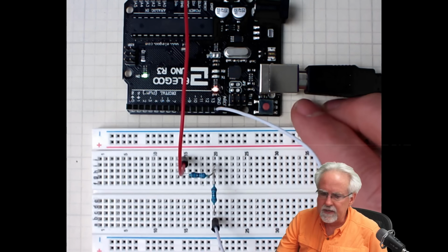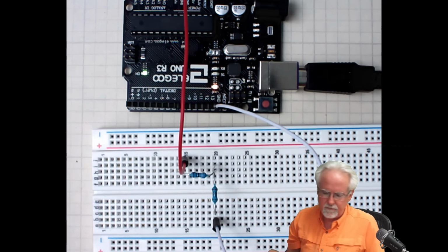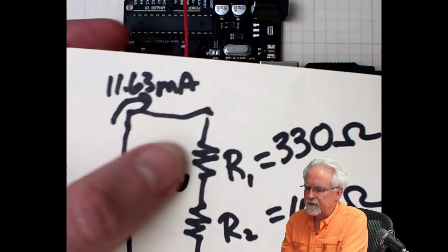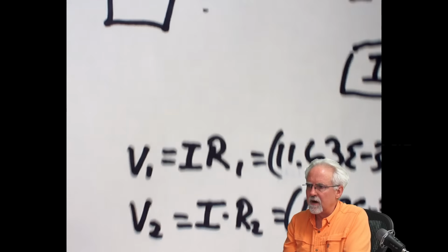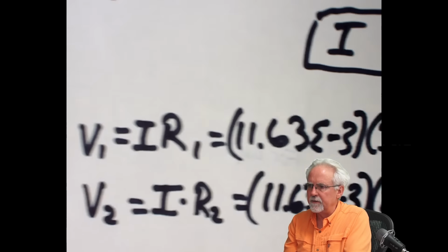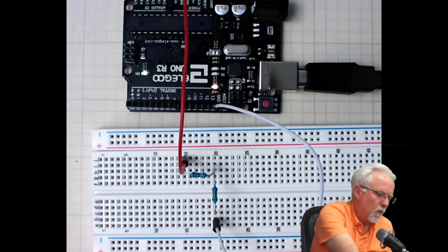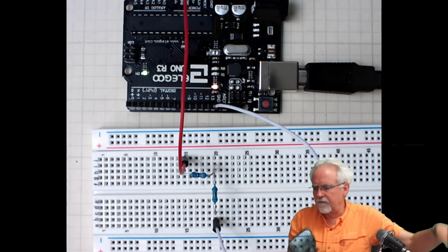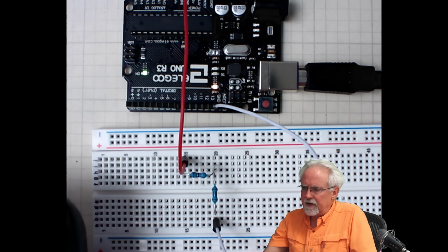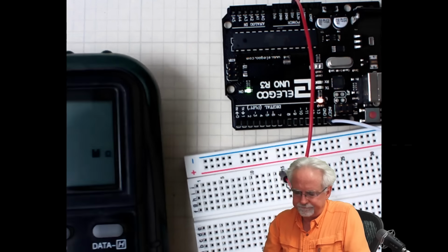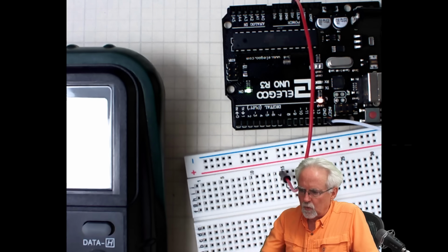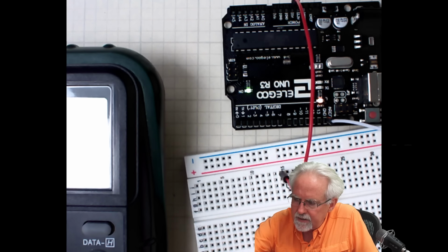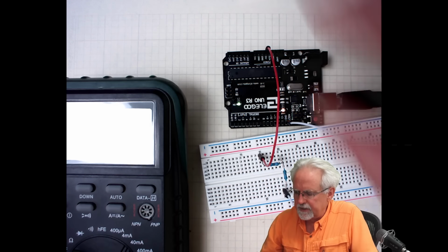All right. The easiest way to check it instead of measuring the current is to measure these voltages across R1 and R2. And so let's start by measuring V2. All right. So what I have here is, and if you don't have one of these, if you're going to be in the engineering arena, you really, really need to get yourself a simple digital voltmeter.